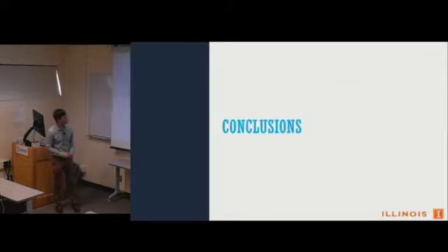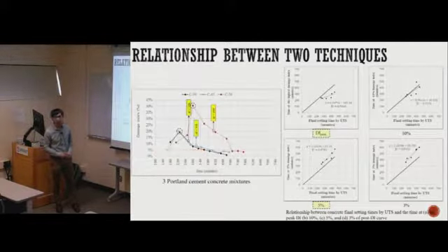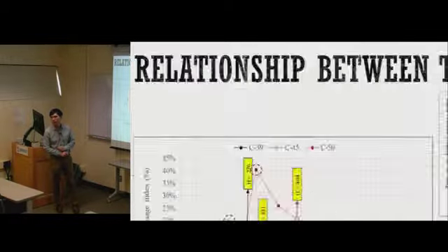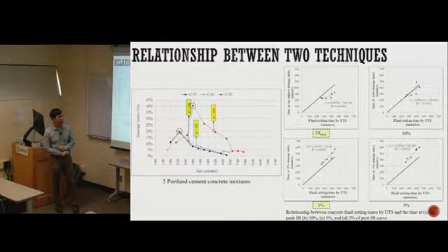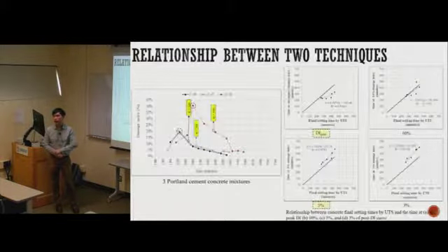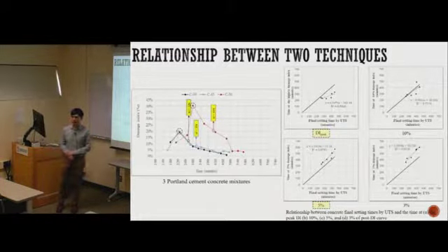I don't assume it's linear. I plot it, and you can see here that linear has a pretty high coefficient of determination. Here it is low, right? But it increased. You mean the points below the lowest number and above the highest? Yes. So usually final setting time is not going to be low here. It will be somewhere above 200, unless you use a very quick accelerator. But I don't think it could be.